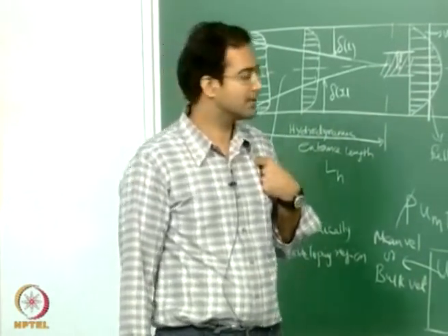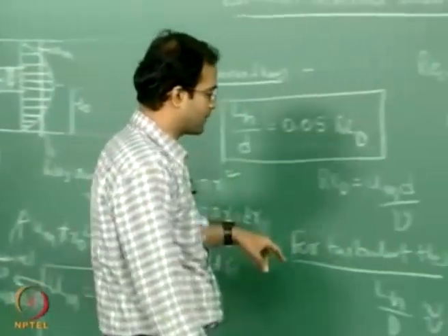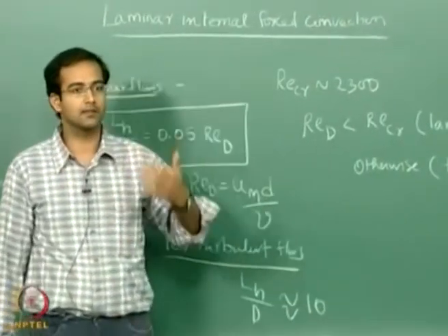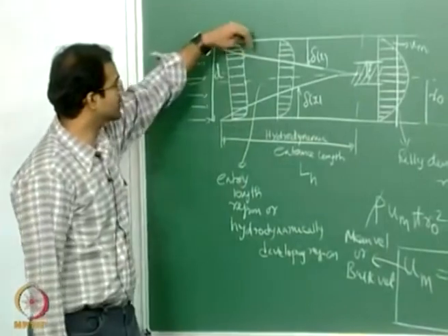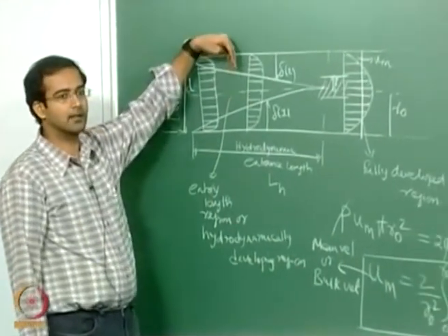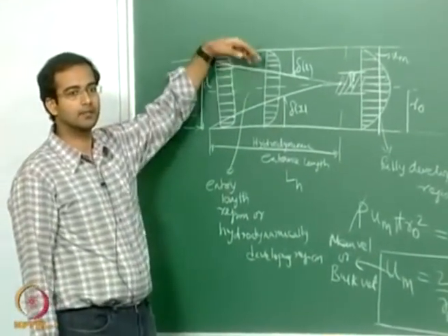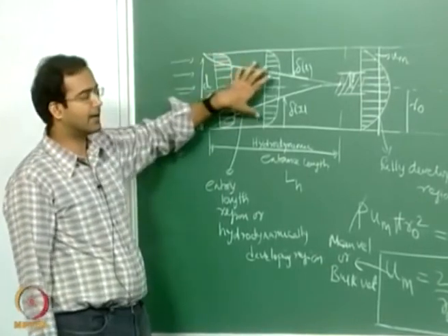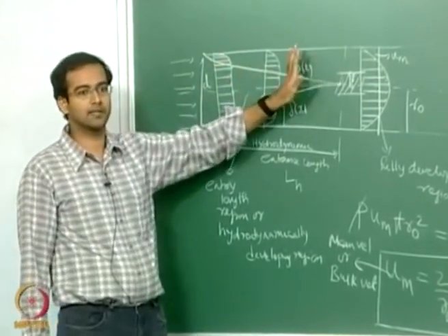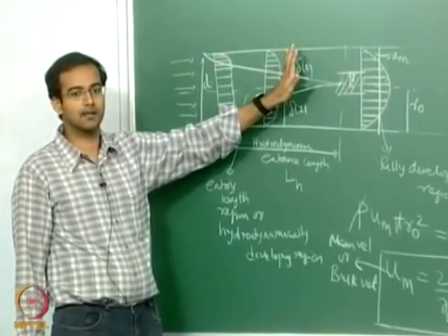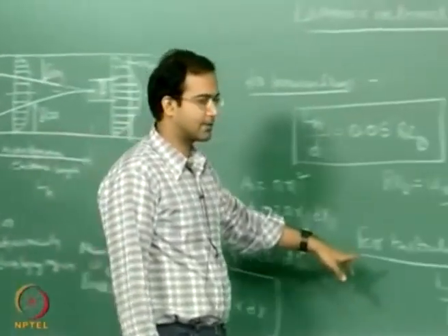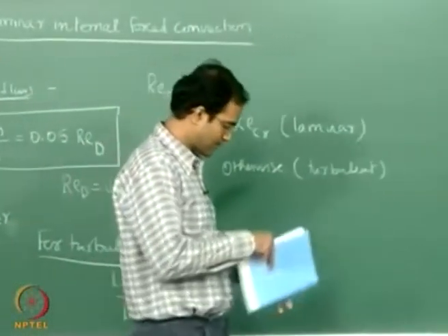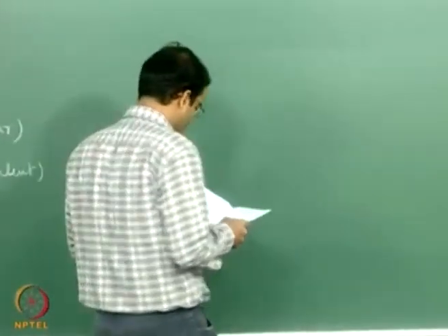The reason is that turbulence promotes intense mixing or diffusion of flow. The mixing takes place due to the gradients along the y direction, so there will be intense mixing, and therefore the profile can reach a fully developed state much earlier in the turbulent case than in the laminar case. Therefore the entry lengths are much smaller in turbulent flow than in laminar flow.